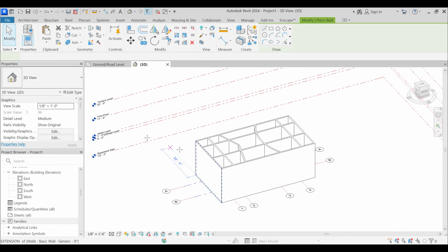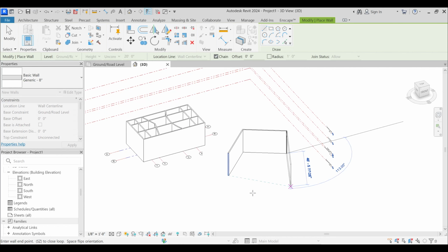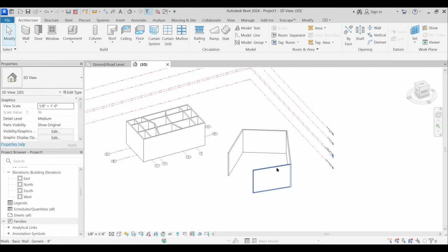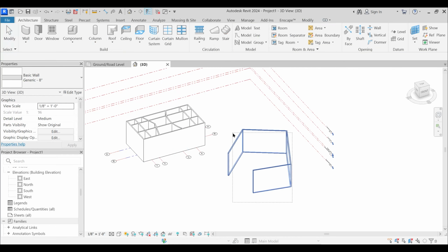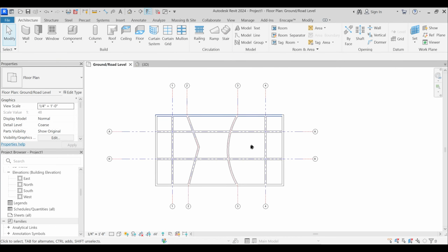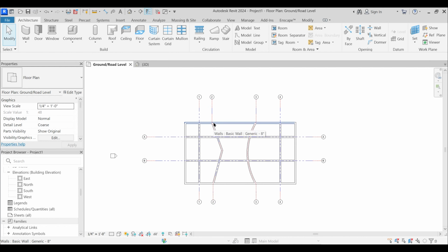See, if you want to draft a floor plan, bring the AutoCAD floor plan into Revit and make walls, you won't build it in 3D. Of course, in order to draft that particular thing, you need to go to the floor plan, insert that AutoCAD floor plan, and then work in 2D only. But that thing will get elevated in 3D. Okay.